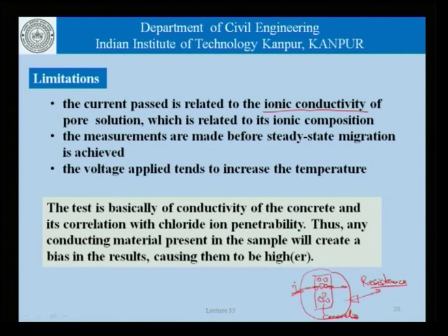The measurements are made before steady state migration is achieved. So, it is not a steady state measurement. We put the apparatus together, switch on the equipment and start measurements right away for a period of say 6 hours. So, it is not a steady state measurement. The voltage applied tends to increase the temperature.